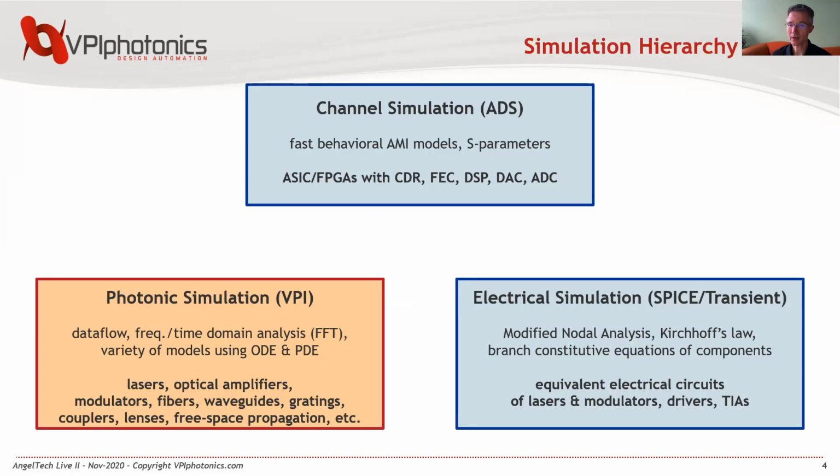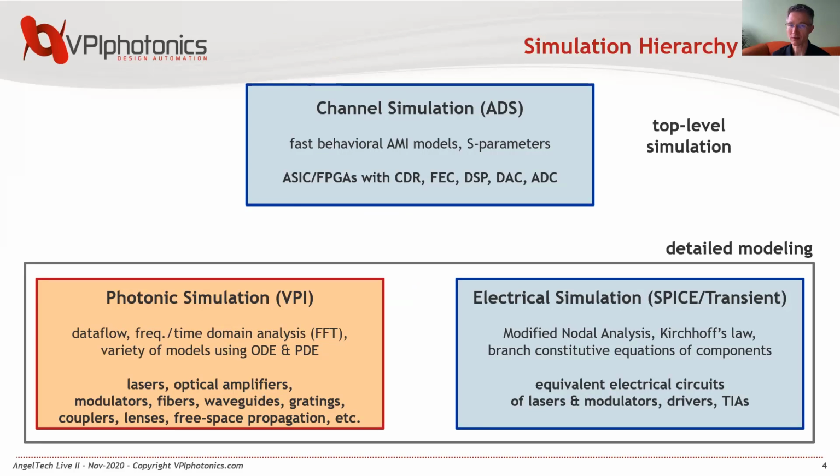Considering the simulation hierarchy, there are two different levels which you can account for. At the bottom part, we see here detailed modeling approaches, where we would have on the optical domain, for instance, our photonic simulator provided by VPI, allowing you a detailed analysis of lasers, modulators, amplifiers, etc. And on the electrical circuit simulations, using SPICE type of simulator, performing, for instance, modified nodal analysis to account for the aspects of drivers, transimpedance amplifiers, etc.